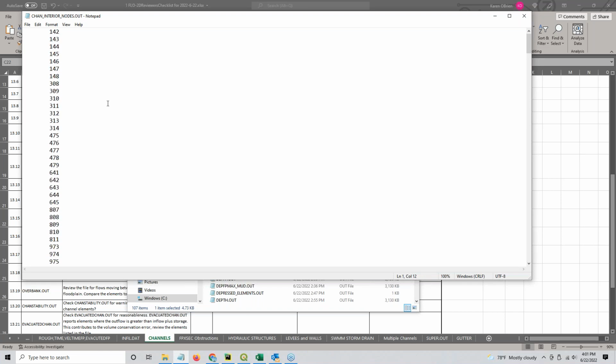And maybe if this was a district project or a project with a really complicated channel, I might be concerned about that. But since there's no tributaries, and the channel doesn't have any weird changes in the bank, the left and right banks are very uniform and very normal. There are no major spaces in between any cells on the left and right banks. There's no terminus between channels. It just goes inlet to hydraulic structure to hydraulic structure, hydraulic structure to outlet. So I wouldn't consider this a channel that needs to be checked.